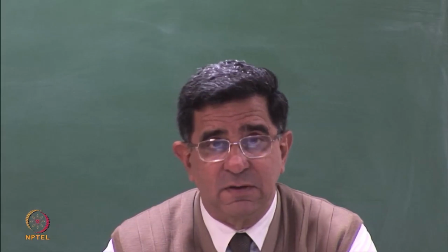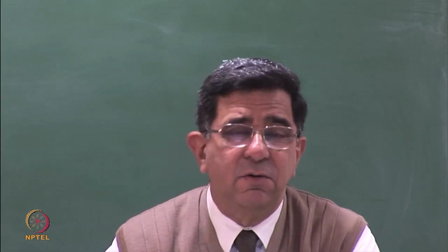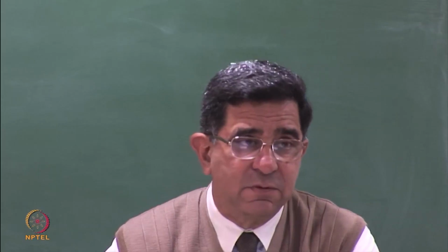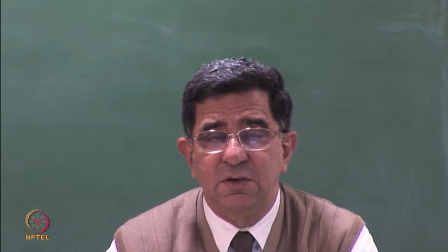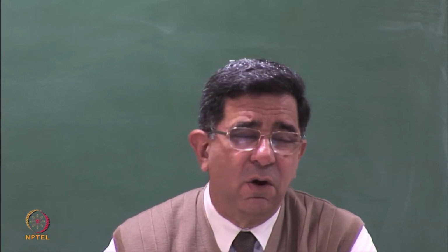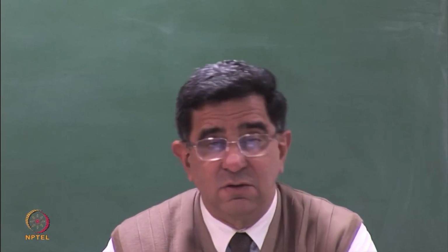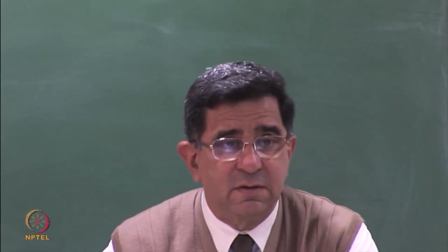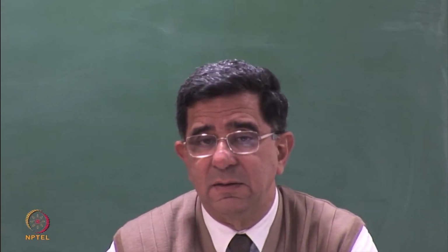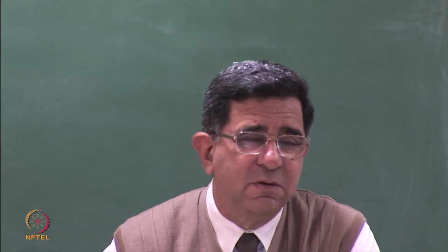If both of these are not present, then there is a tendency to maximize depth. But I've already told you that to go to deep depths we need stability measures along the sides. So normally we would not go beyond 7 to 8 meters of excavation. That is not to say that we cannot excavate to 20 meters, but then you have to put retaining structures. You have to ensure that there is no instability while you are filling up the waste. So normally the depth will be 7 to 8 meters.